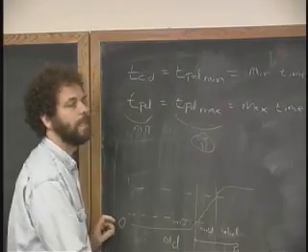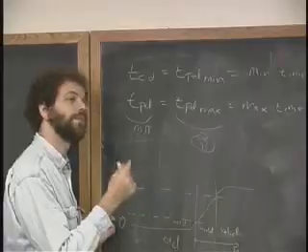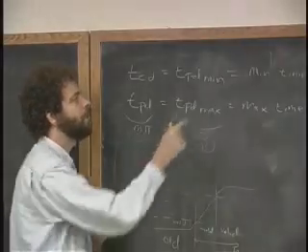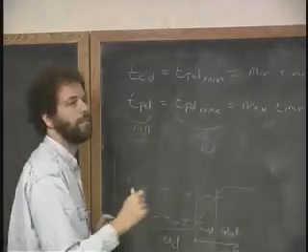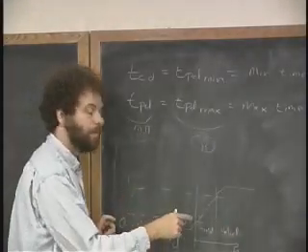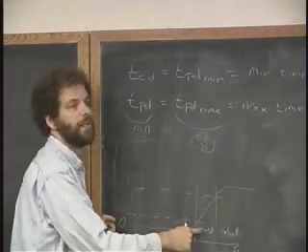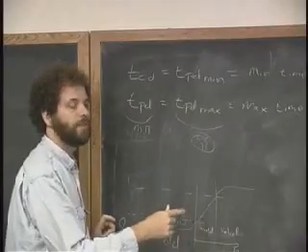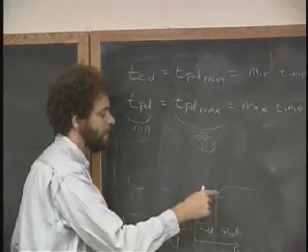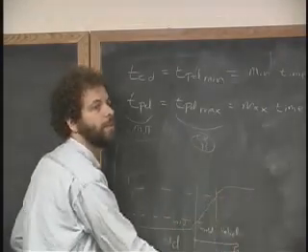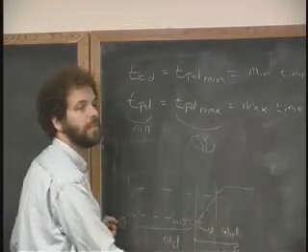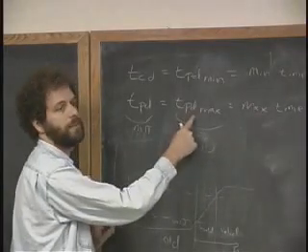Well, the answer is that it guarantees it will continue to produce the old result for at least TPD min, the minimum amount of time to propagate through the circuit. The minimum amount of time for invalid stuff to propagate through the circuit. And then the question is, okay, once I finally send it the valid new stuff, how long does it take for the valid new output to happen? And the longest that could take is TPD max.